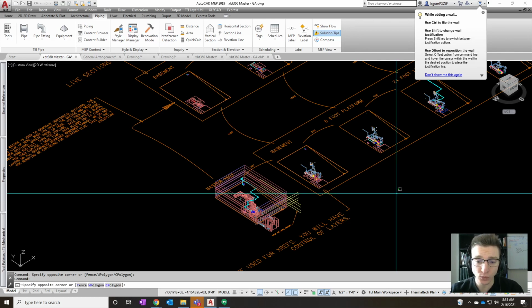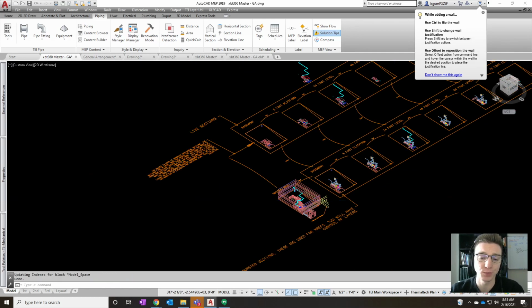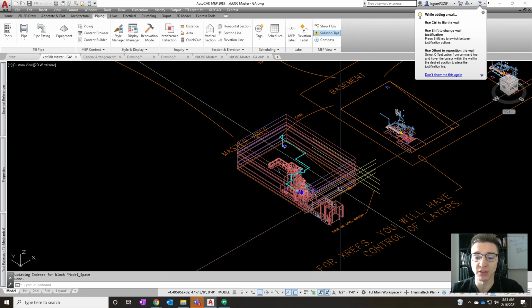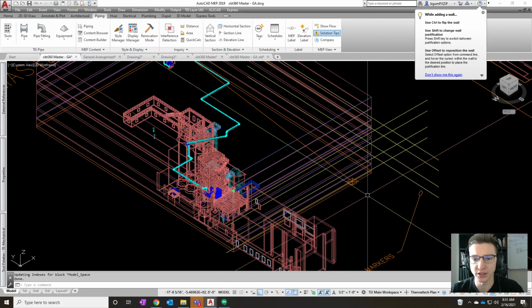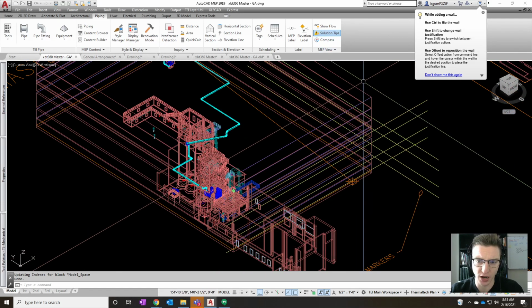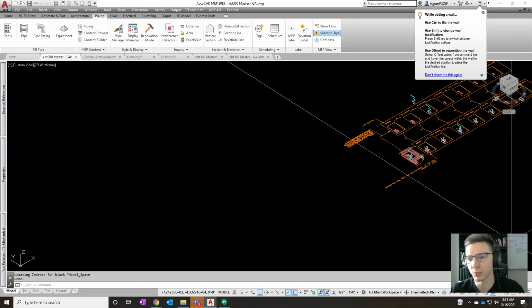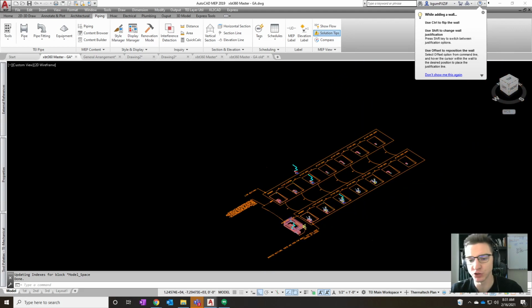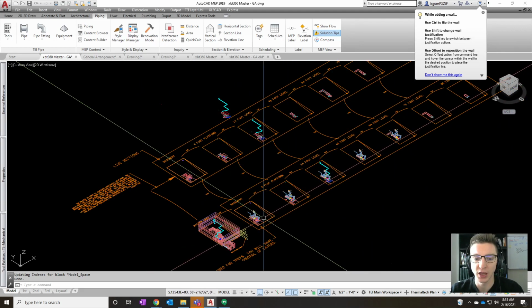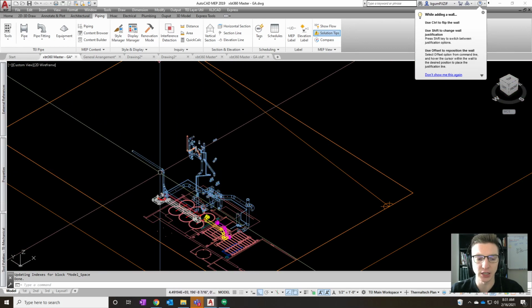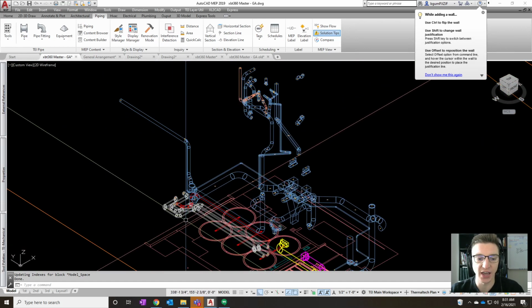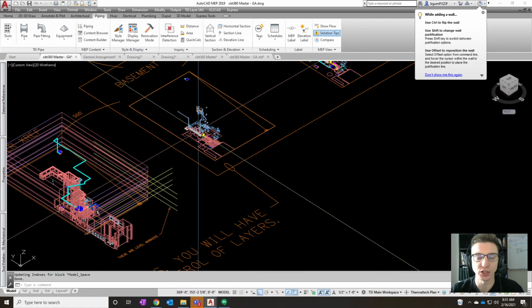And so what I've done here is I have a 3D model, which is right here, and then I've cut section cuts all the way around it. That's this purple and pink box that you see. And what I've done is I've generated, sorry, excuse me, a little bit of performance issues here. I've generated all these floor plans here. And then what I've done is I've then taken my AEC objects and I have duplicated them on each layout.